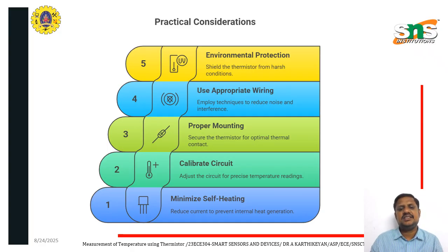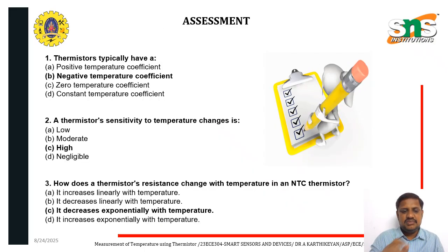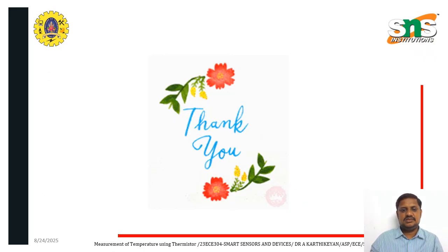And for practical considerations, we have five important parameters: minimize the self-heating, calibrate the circuit, proper mounting, use of appropriate wiring, and environmental protection. These are the practical considerations of the thermistor, and this is a simple assessment. Thank you.